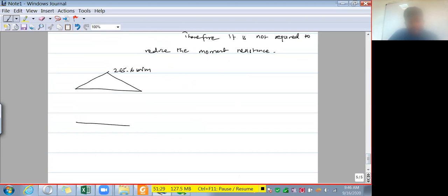And our shear force diagram is this: 127.8 kilonewton. BMD, SFD. Now, if you take the combined action at midspan, the combination is 255 and 0. If you take the combination at the support, it is 127.8 and 0.